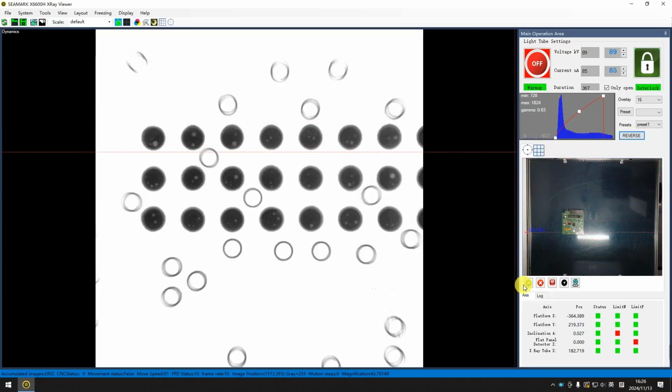And here is the navigation image where we can do the navigation to move the position. The first button is to put an OK mark on the board. The second is to put an NG mark on the board. After checking whether a chip is OK or not, you can place the mark on it.